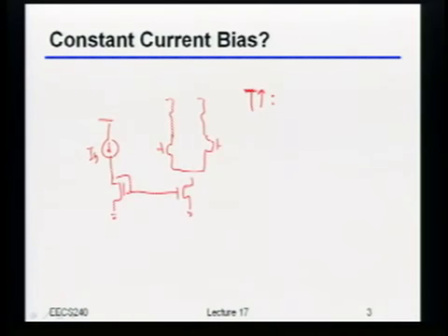Noise goes up. Okay, that's true. The noise would go up. That's just kT. That's a little bit trickier, but okay, that's true. Actually, the noise would indeed go up. But remember, T is an absolute temperature, so if I go from like 300 Kelvin to 350 Kelvin, that's usually not too bad. But you are right, the noise would go up. The band gap would change, so VT would increase. Okay, so you're right, the threshold voltage would go down. Does that matter too much in this particular design?